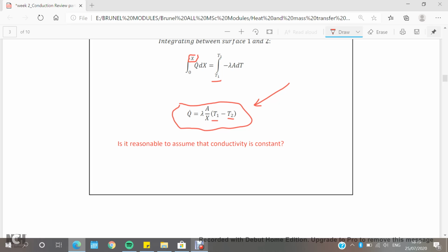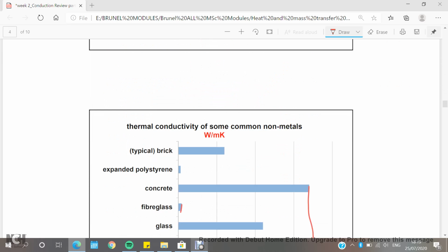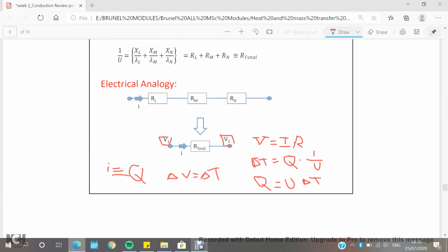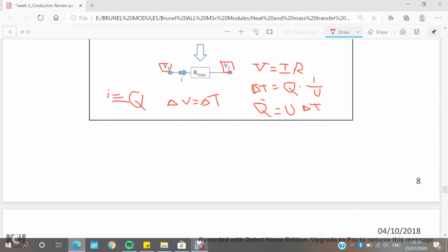This is for the unit thickness, like this one, x over lambda, which is inside the U value, but here we don't have A in our case below, so this can be called heat flux. For example, if I put it here, Q double bar equals Q, which we had before, divided by A. Heat flux is the heat transfer rate per unit area.